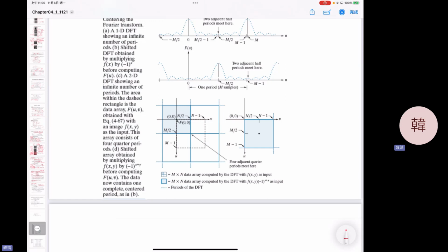Like this one is 300 and this is 200. So if I'm going to do this, especially in the frequency domain, the better choice is a 500 point transform. If you extend this to 500, there are zeros there, and you also extend this to 500, so there are zeros there. In that sense, when you do the convolution, the Fourier transform followed by multiplication gives you the same result. So we can see the result.